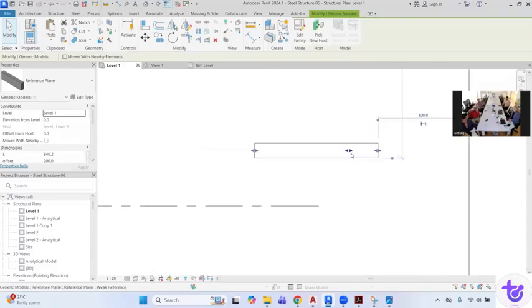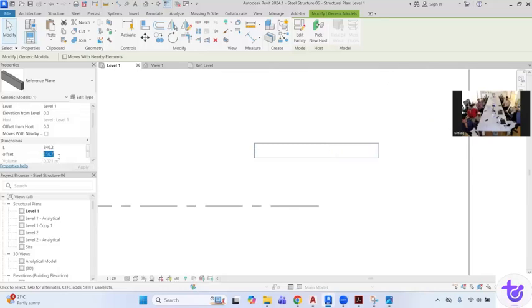For the weak reference, it is showing us the shape handle. There is nothing else in the family, but still there is a reference plane which is having the weak reference. It is giving you the shape handle to change this. Now you can see the offset value is getting changed here. And if you change it from 310.7 to 150, it will change here.